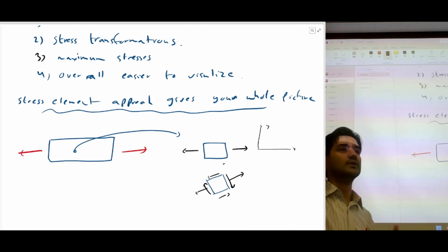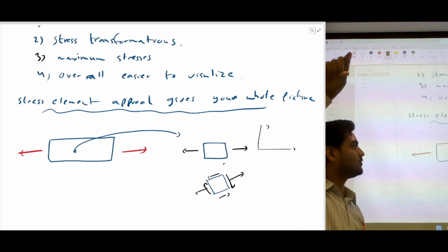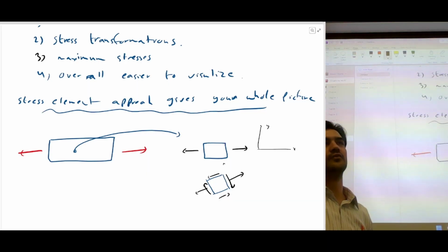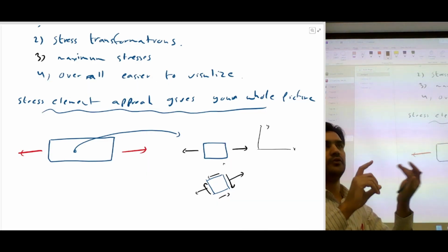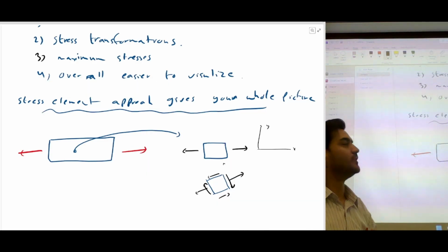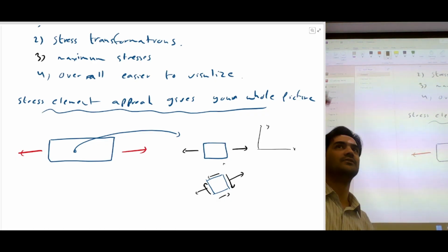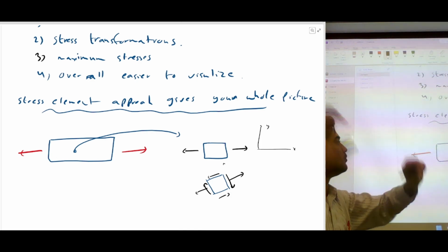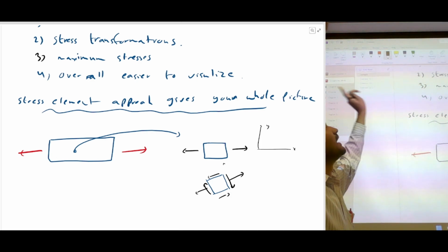For example, if you want to design a machine, or if you want to design this floor, all you have to figure out is how thick the floor should be, right? So you can calculate the external loads. You know how much snow it's going to have on a yearly basis, what the wind loading is, and how many people on average will walk on the floor. You know all those things, and you can convert them into an external load. Once you have all those external loads, you can calculate the reactions at the support, right?